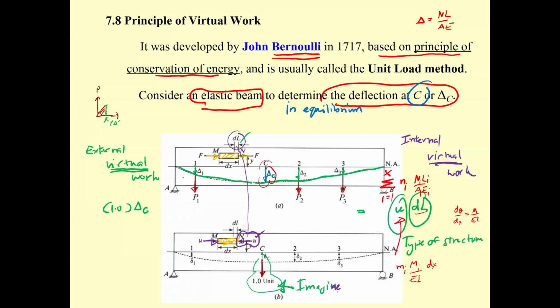And for the beam, the deflection function is a continuous function, so this one integrates from x equal to 0 up until x equal to L. So this term for the beam and the frame is going to be the integration from 0 to L of m, due to the 1.0 unit load, and M, due to the real applied force, times dx over EI.